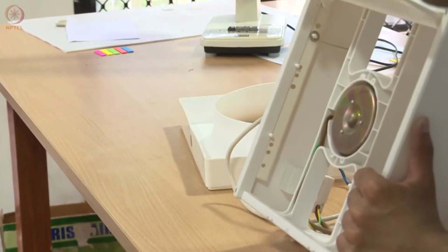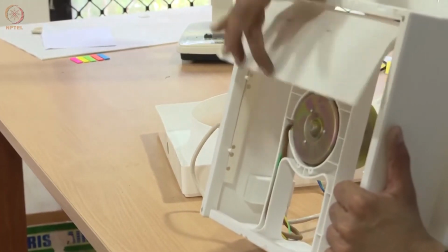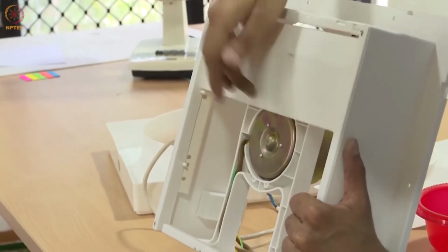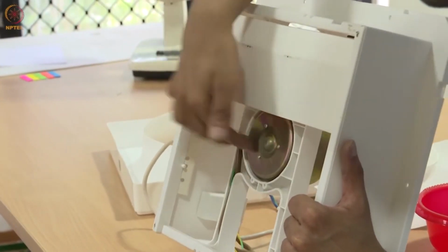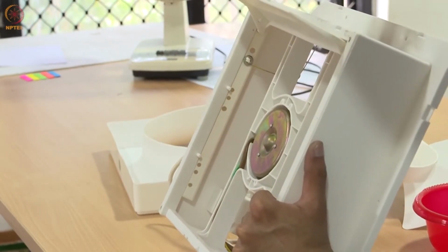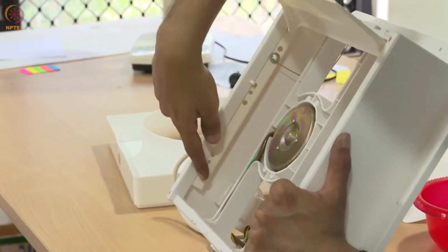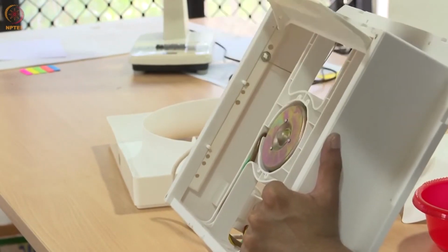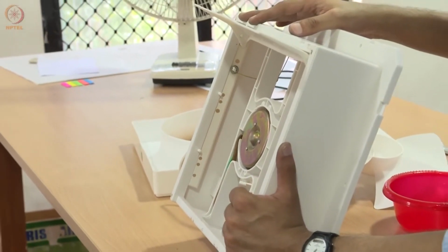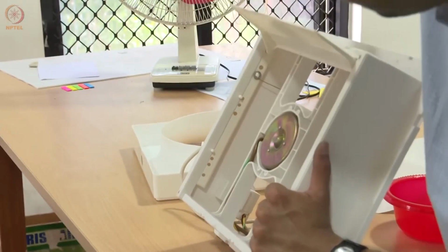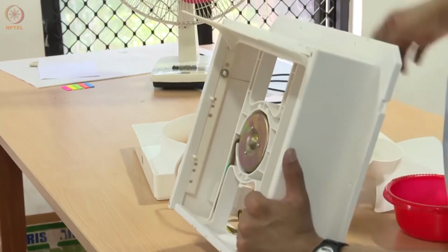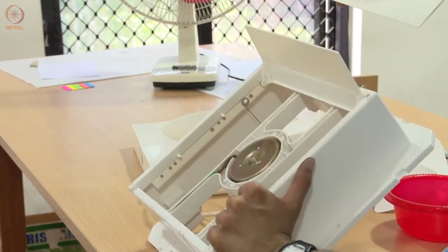So basically, we have this mechanism. As you can see, as I swing this louvre, we call it this louvre or this guard, back and forth, you can see this slide moving up and down. So basically, what we call this is a slider crank. This is the slider part of the mechanism, and this is the crank part. So you have to look at a slider crank inversion of a 4-bar mechanism to understand what this exactly is. When one of the blades moves, it couples the other blades together, so they always move in a synchronized fashion.